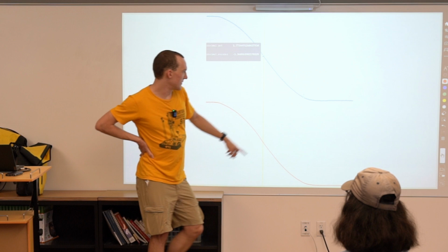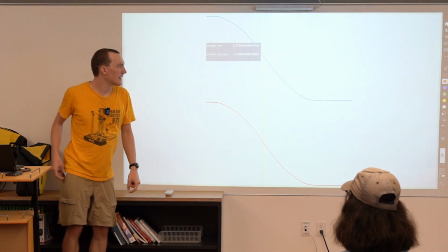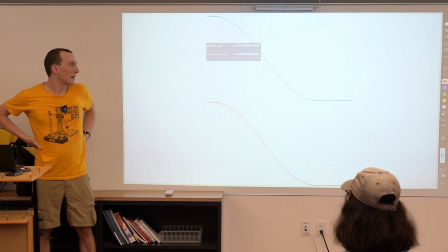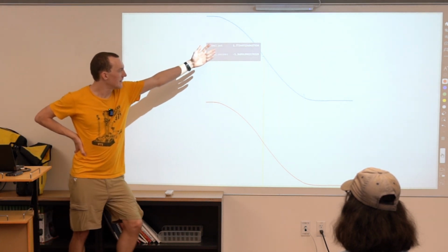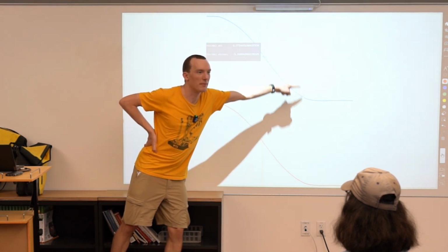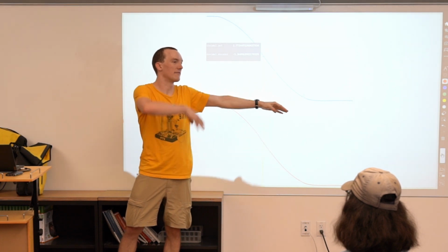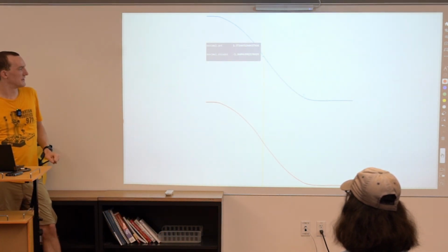It's also the case that there's a bit more noise if you squint at this. The potentiometer is generally subject to greater imprecision than the quadrature encoder. So if we try to use this directly, this would be sort of close. But then what happens if we get here and we see a blip? We don't want the mechanism to suddenly jump. So your choices of sensors matter, is all that's saying.